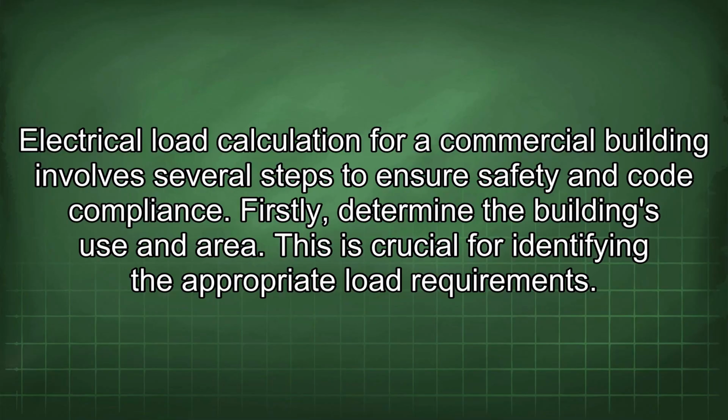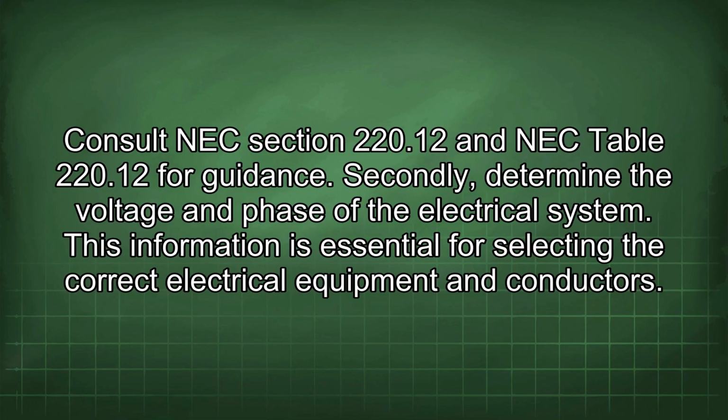Electrical load calculation for a commercial building involves several steps to ensure safety and code compliance. Firstly, determine the building's use and area. This is crucial for identifying the appropriate load requirements. Consult NEC Section 220.12 and NEC Table 220.12 for guidance.